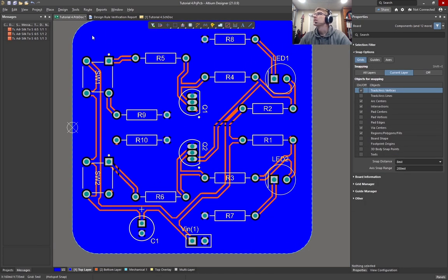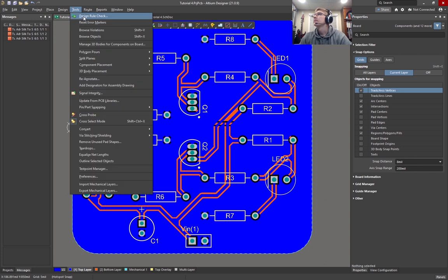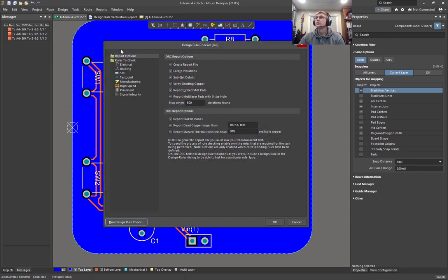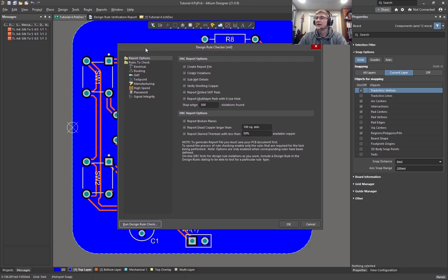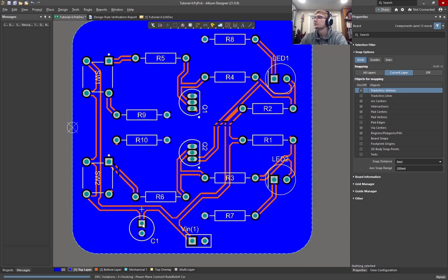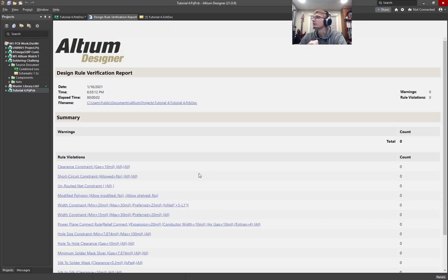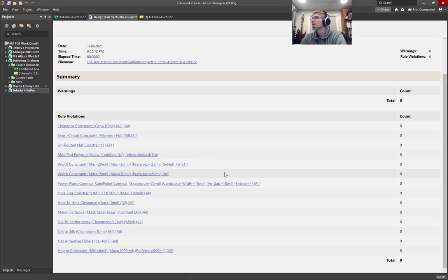Okay, so now, finally, we want to keep adjusting our rules. We want to keep adjusting our actual routing and component placement, and we want to adjust which things we waive. For example, sometimes it'll be particular, like the expansion rule in a board like this. I just happen to know, and you might too, that a slight shift in the size of the solder mask won't affect your board.